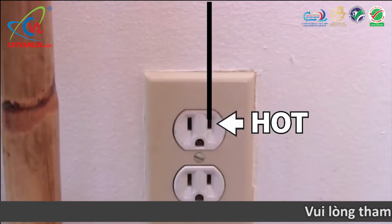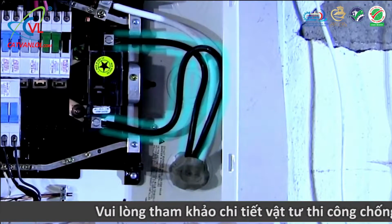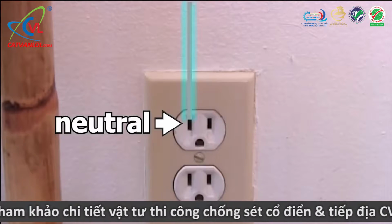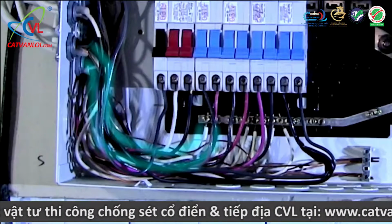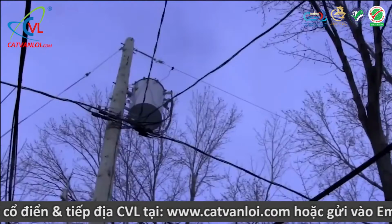Behind the hole called hot, you'll find a wire that runs behind the walls, and eventually goes to a breaker in your breaker panel. From there, the electricity goes behind the breakers to one of these thick black wires, and then outside your house to a transmission pole and transformer somewhere. The other hole, again called neutral here in North America, also goes to that breaker panel, but not to any breaker. Instead, it goes to this metal bar. From there, the electricity goes along this thick white wire, and then outside your house to the same transmission pole